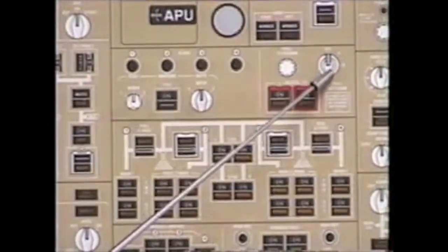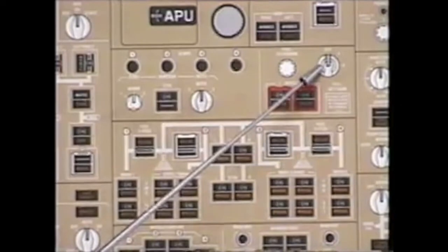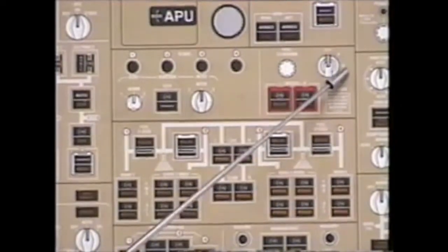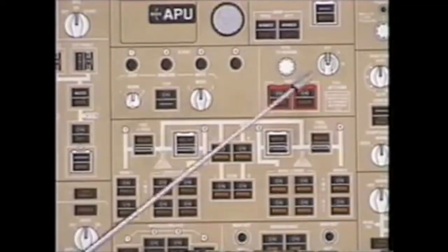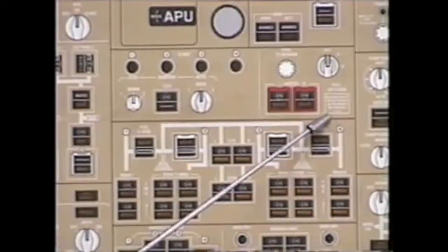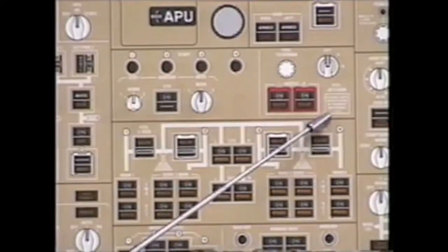Fuel jettison selector: if in the process of dumping fuel the selected controller fails, the primary ICAS will indicate this. However, the other controller will automatically step in and continue to dump. Please remember that fuel jettison is not permitted while operating the flaps between positions 1 and 5 or 5 and 1.